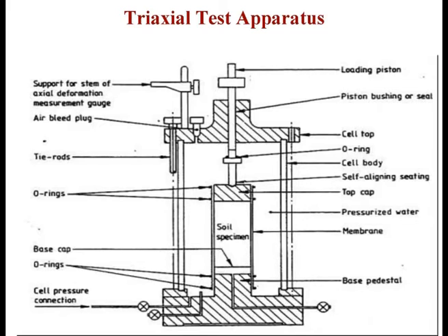The thing that is non-standard about the triaxial test, that you don't see in a lot of structural testing, is the facility to apply confining pressure or radial stress to the soil specimen. The reason is that it has been found that the behavior of soil is stress dependent. So you want to apply a lateral pressure to change the stress so that you are able to control the behavior of the soil. In order to do that, you need a rubber membrane.